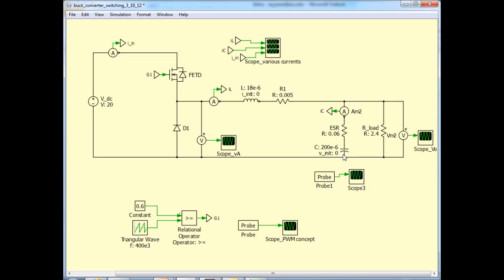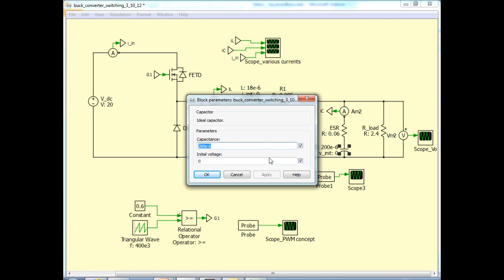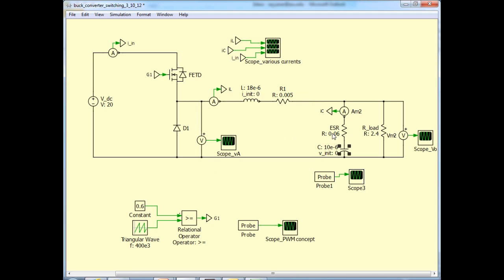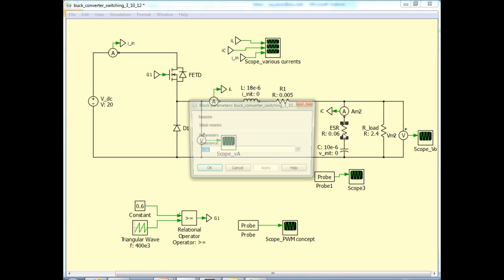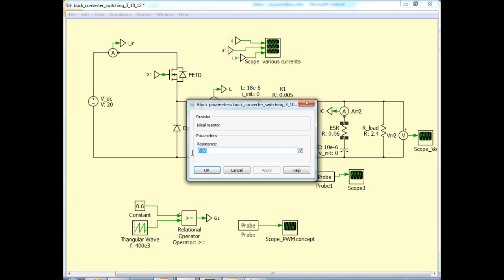So if you recall, based on just the capacitive impedance, I think we require a capacitance of more than 5 or 6 microfarad. So let me use a film capacitor or multi-layer ceramic of say 10 microfarads. That's 10e minus 6, and the ESR is negligible. So instead of 60 milliohms I would use say 1 milliohm, so it's 0.001.